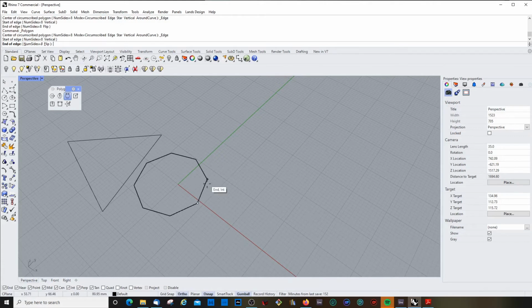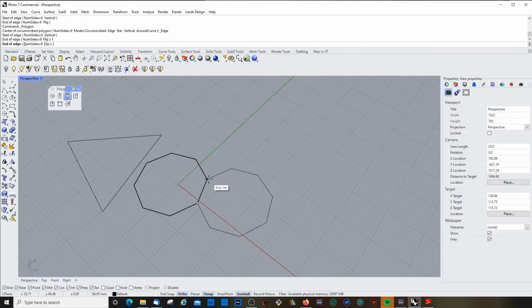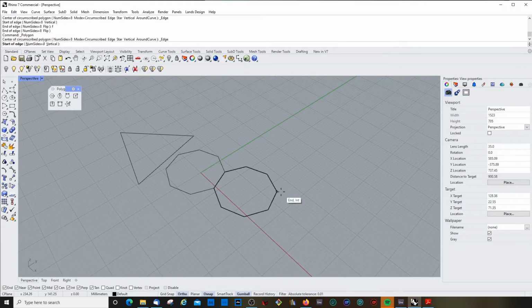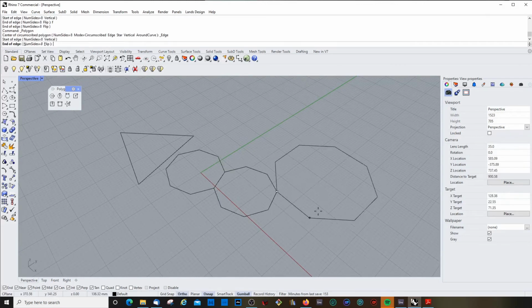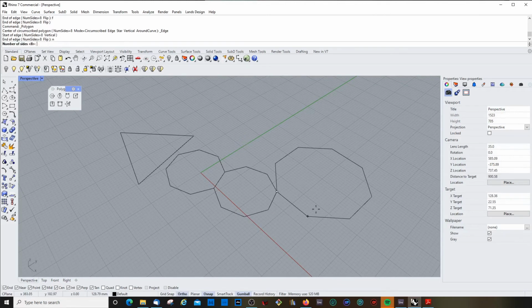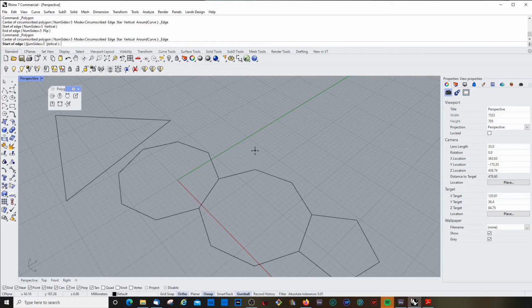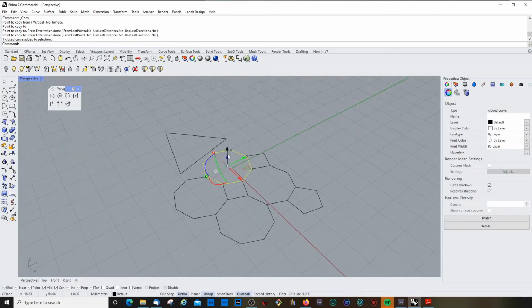You can, for example, if I would like to draw the same shape but flipped, then you just type F here and it flips it in a different direction. And what is also good, even though I started already with the drawing process, I can actually change the number of sides. I can say 5 and draw this like this. That doesn't work, but here I could of course draw a rectangle. That could work. Number of sides 4. Now if I do this, it should actually fit in here. And then of course you can extrude them if you want again.